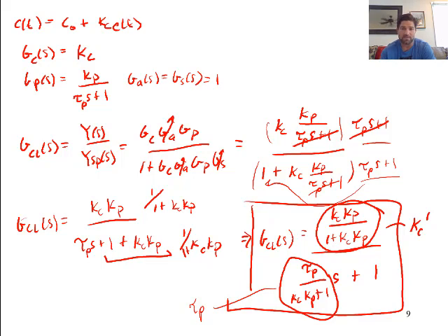We can see here that tau p prime is always going to be less than tau p, because the denominator down here is always going to be greater than 1. These are positive terms, and Kc has to be positive for stability. So by adding the gain term, it makes the time constant for response faster. In general, the effect of the gain on the feedback control is that there's going to be offset if it's P-only by itself, and it decreases the time constant of the feedback loop, which means a faster response.